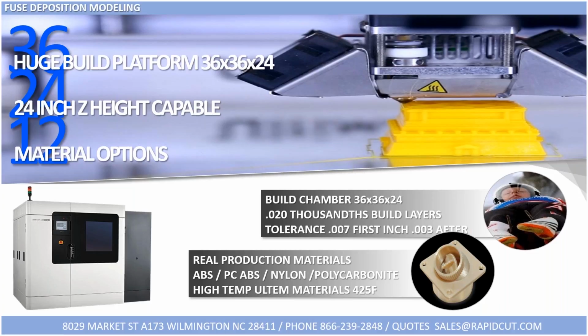Again, the big benefit here is you're dealing with real production materials. There's a couple of them of note that are unique to FDM only, and that would be your high temp applications. There's 3 different high temp materials ranging from 375 up to 425 degrees F, making it the most usable in the high temp area of the 3D printing processes using plastic. And of course, those are going to be nylon based materials.